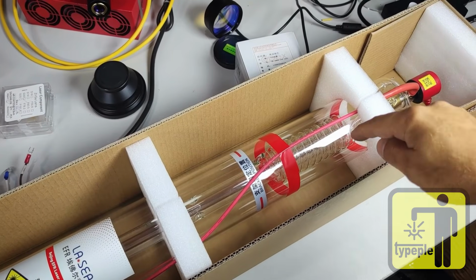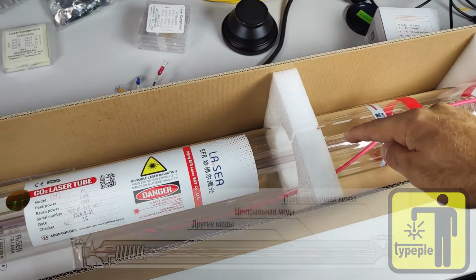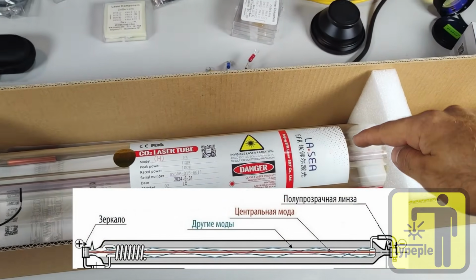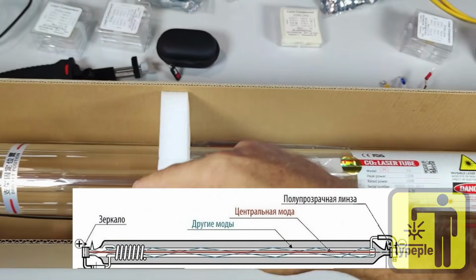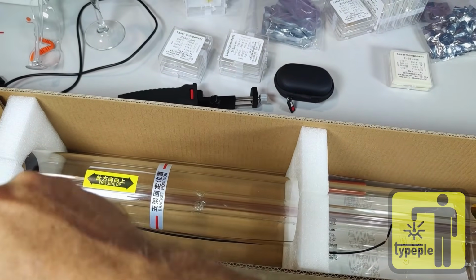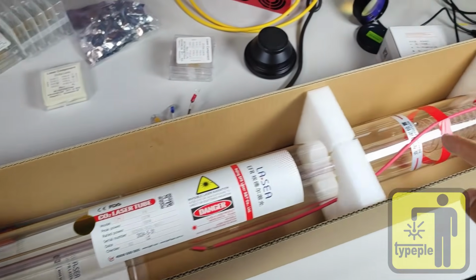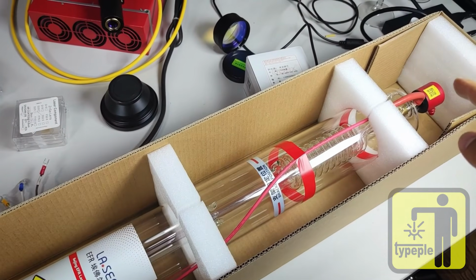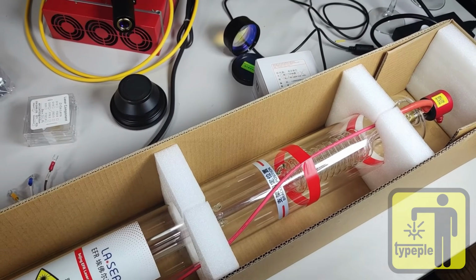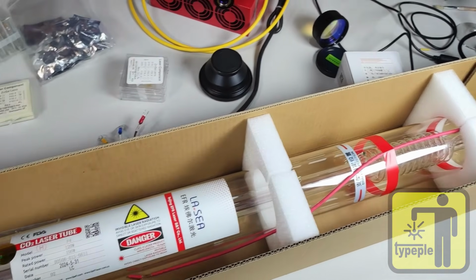And multi-mode means the resonance of our electromagnetic wave inside the very thin tube happens in such a way that the beams bounce in different directions. And only the beam reflected properly and correctly from the back wall due to resonance in our tube gives us the TEM00 mode at the output through a semi-transparent mirror. That is, clearly focused into one tiny little spot.